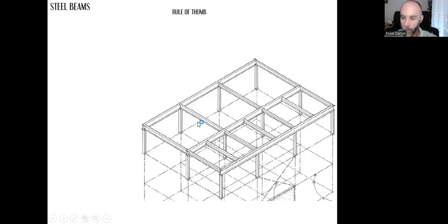Here is a rule of thumb that you can use in your project for the height of the main beam. If I want to make a decision for the proper, necessary height of a main beam, then I can just divide the span by 20. That's the span that I want to create according to my unit decisions.